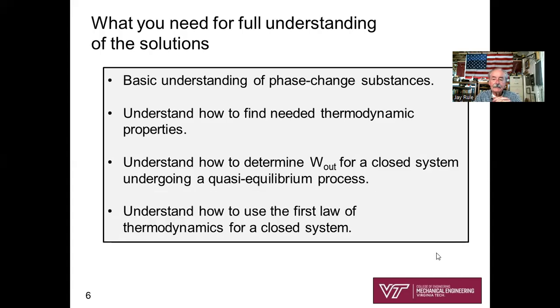And finally, you need to have an understanding of how to use the first law of thermodynamics for a closed system. One thing I've been telling folks is whenever in a word problem you see the words find the heat transfer, or heat transfer given, or things like that, that's nearly always a clue that you're going to be writing down the first law of thermodynamics for a closed system to solve that problem.